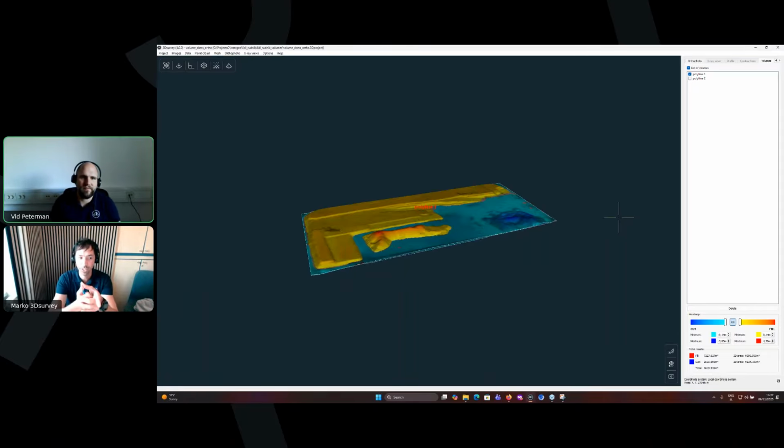So there is a free version? Yes, there is a free version of DJI Terra which only allows you to convert the raw data. So Alexander, you need this one, and then you can do it without paying for Terra for the scanner, okay? You just need to get the last file from the Terra free version, and you are able to continue in 3Dsurvey.